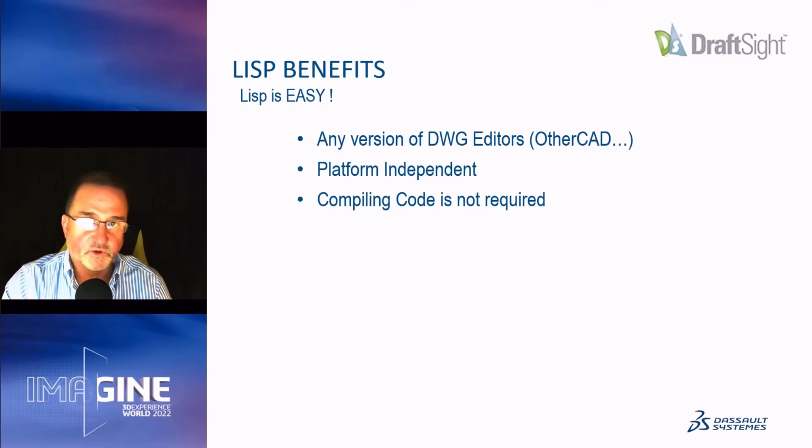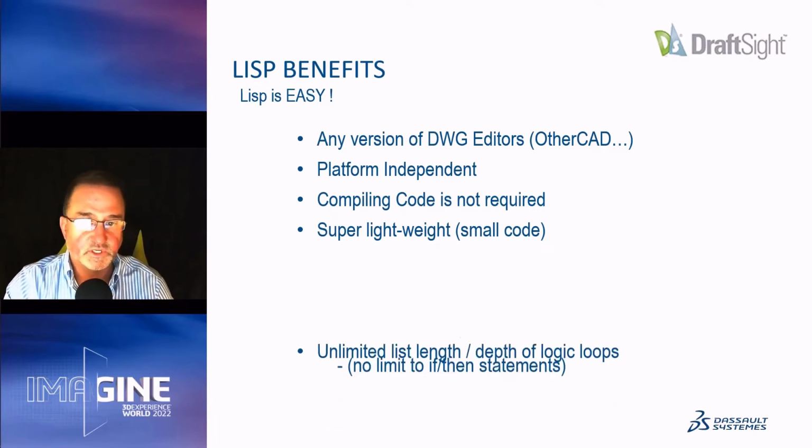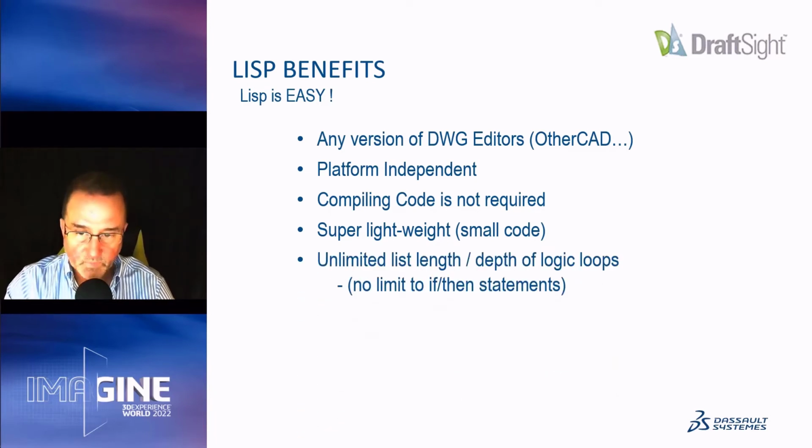You do not have to compile your code. So I can basically take that text file that I wrote, my startup.lisp file, and I can run it without compiling it, without doing anything special to it. I can just run it as it is. Because I don't have to compile it and because it's just text, these Lisp routines are very lightweight. They're very small. There is no limit to the length of a Lisp routine that you can create or how deep you can go with your logic.